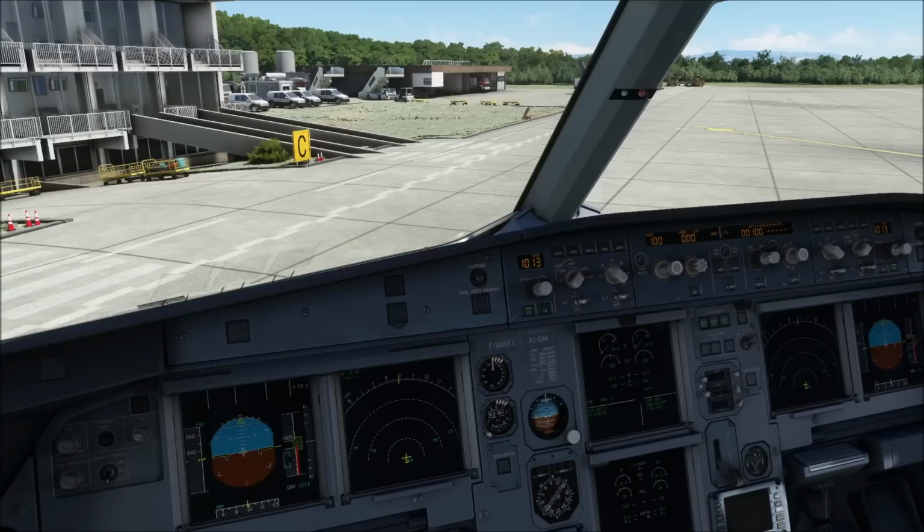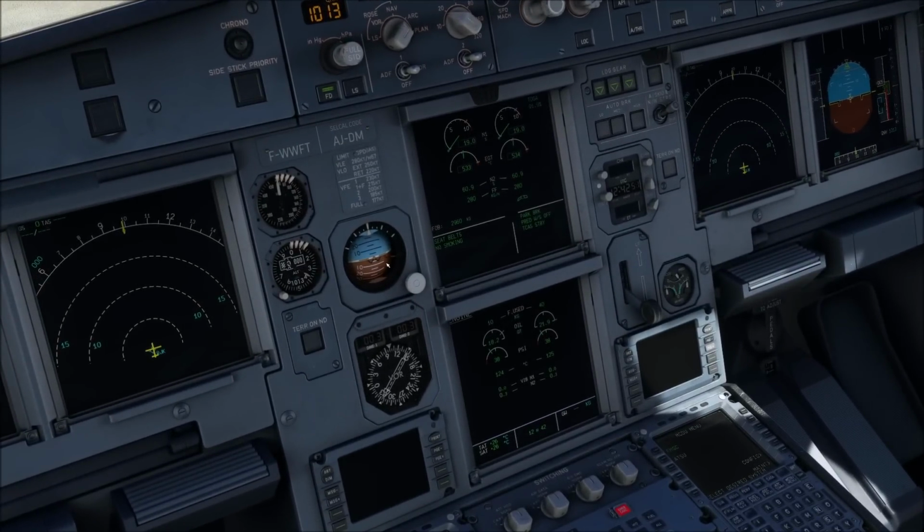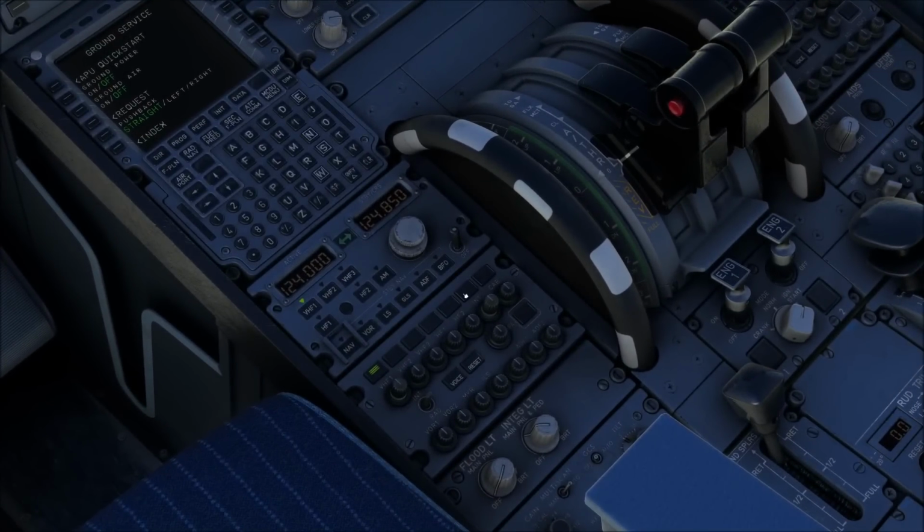Okay, so let's quickly discuss the engine start valve manual operation procedure. With both engines shut down, you would basically aim for a more or less normal engine start. However, there's a couple differences. First of all, the engineer is going to plug himself in, not at the typical interphone position that you would use to talk to the normal ground crew, but at the headphone jack at the engine. And that means he's going to be on the cabin interphone, so all the cabin crew can hear what you're going to say. So before you start the procedure, it is a good idea to tell the cabin crew just to stop talking for a couple moments as you need their interphone.